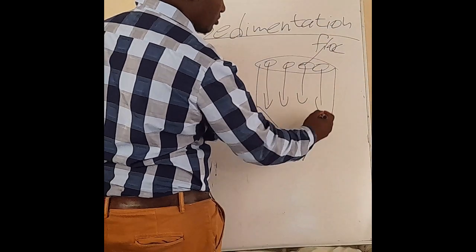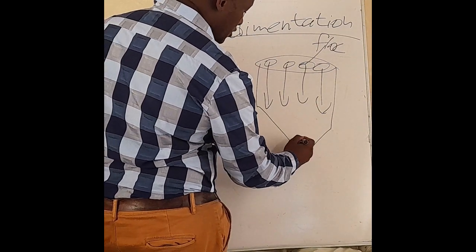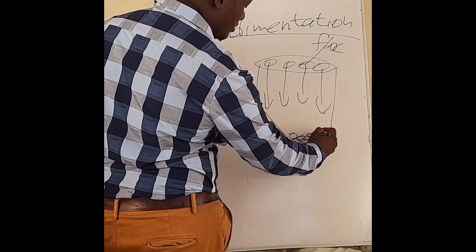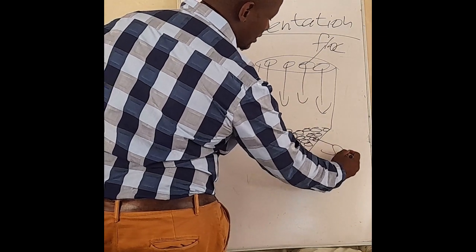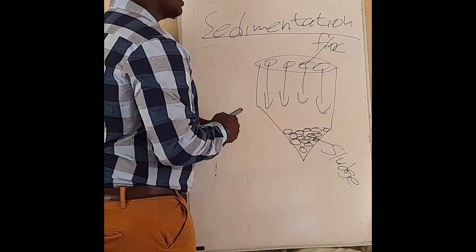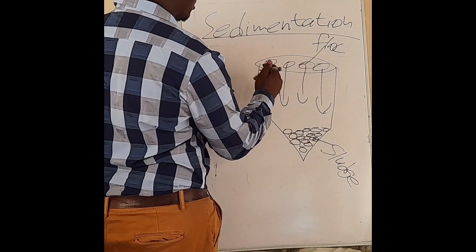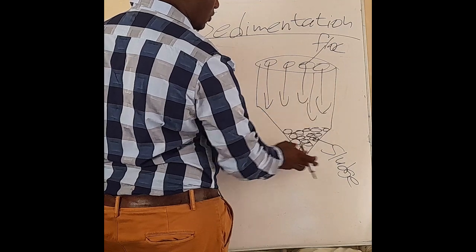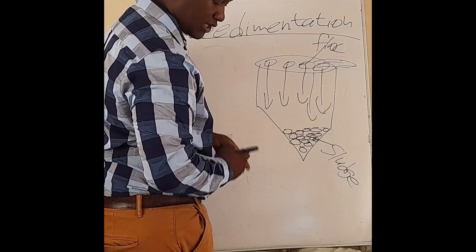It has changed shape, it has changed mass, basically it has changed density. So it will come down to the bottom of your sedimentation tank, and that will then be called our sludge. After some time, hopefully most of the solid particles of that flock were able to settle downwards to form the sludge, and then the water will go to the following stage.